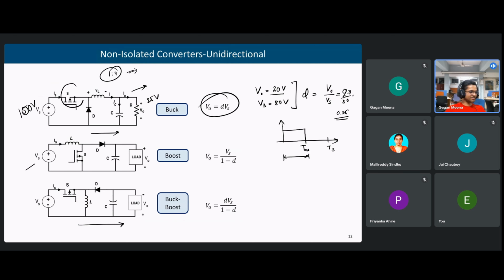So here we are using the switching devices. This will be on for this duration, then it will be off. This will repeat with the frequency, so this is done at high frequency. So the average that we get is, suppose this is V out, and this is Vs. When the switch is on, this diode is not working because it is reverse biased. So when this is on, the entire Vs voltage is across this load.